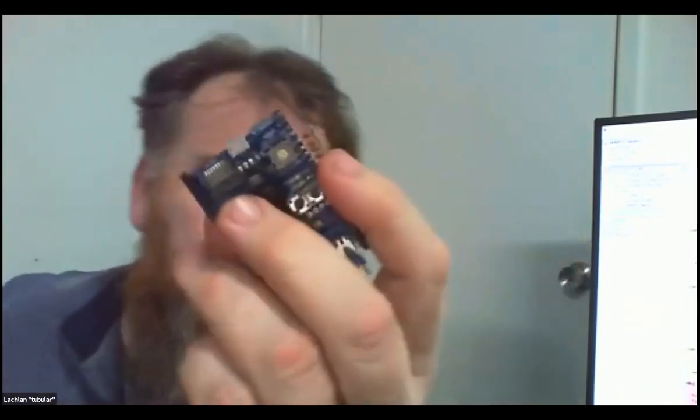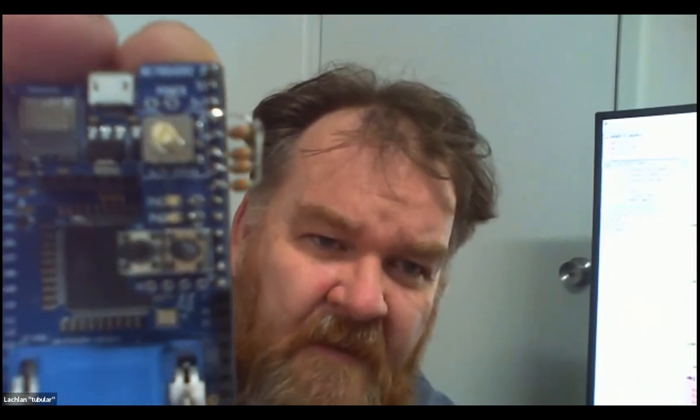This is Cluso's board, and we've got that same rotary idea on Cluso's board there, plugged into the higher pins. So this is on P44 up to 47. This rotary switch has 16 positions, 0 through to F, and it just sets P44 up to 47 to literally whatever's on the dial. The resistors are pull down, and the switch when it makes contact is a pull up switch.